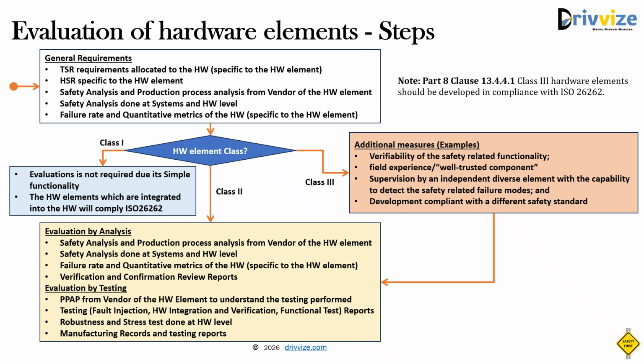For Class 3 components, there are some additional expectations. We need to ensure that the hardware component is developed according to a recognized safety standard. We also need to verify all safety related functionalities and apply proven measures based on field experience or well tested design principles. One more important requirement for Class 3 component is the implementation of an independent supervisory circuit. This circuit should be able to detect failure of the Class 3 components independently.